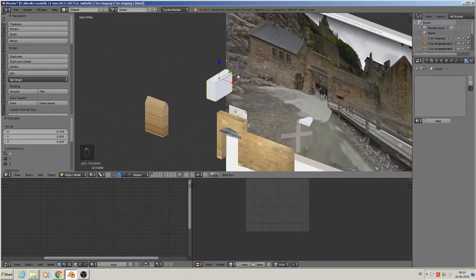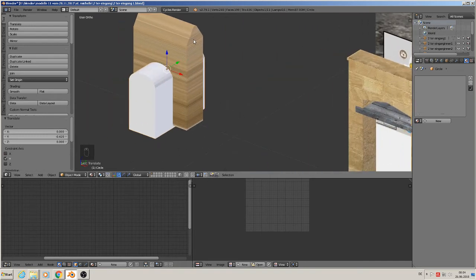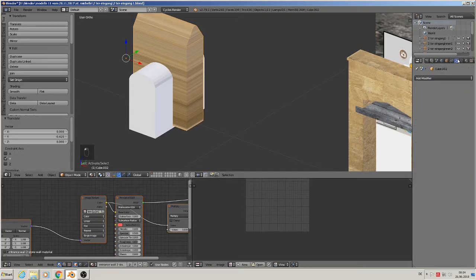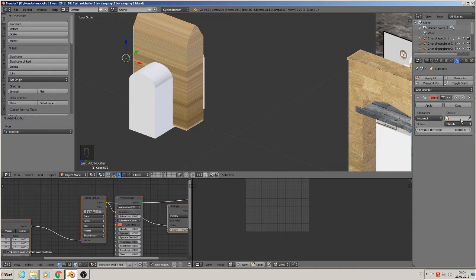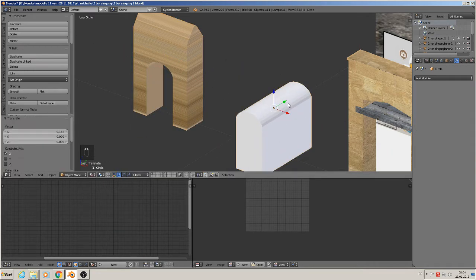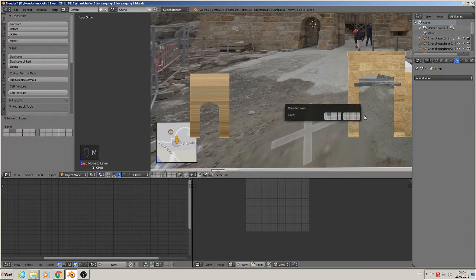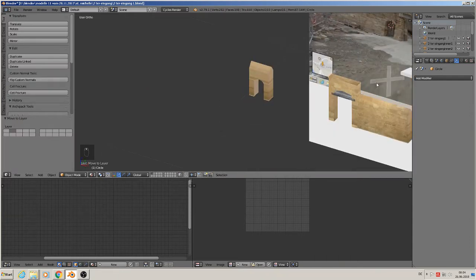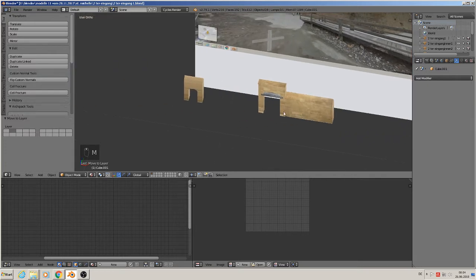So we can now plug that in. The name is circle, so we click that and say here add modifier to boolean. It's called circle and we want the difference, so apply, and the hole is in. We can move that to the second layer, we don't need it in a moment, and that thing too, move to the second layer.